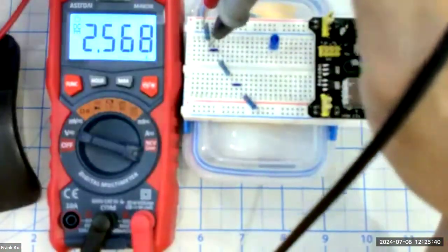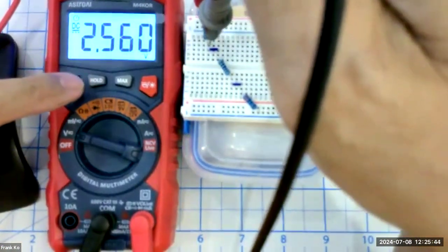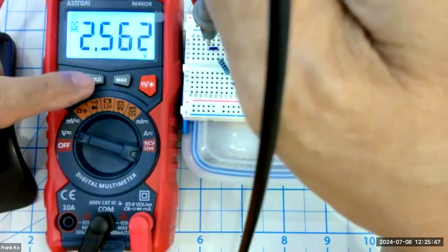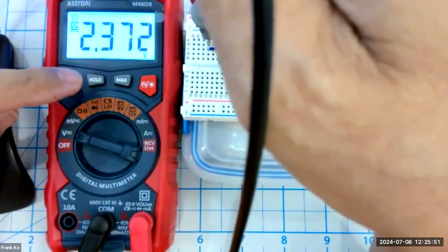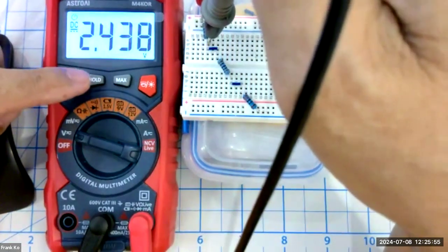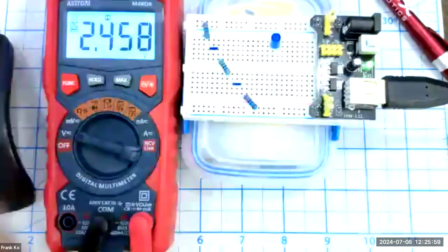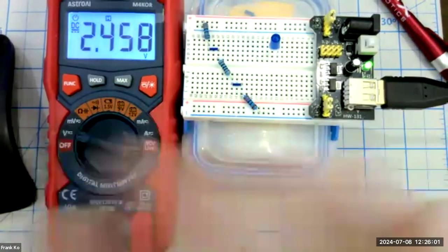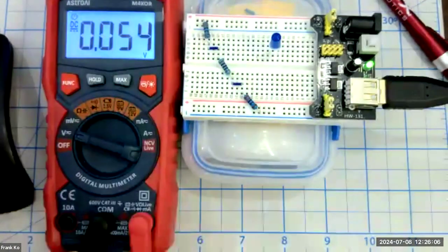Measure, put the probes into one hand, and with the other hand, hold steady. It'll jump around a little bit, but as steady as you can get. Press the hold key. Hold steady. Okay, are we close to the 2.54, 2.45? Not bad. Now let's go ahead, unhold, and let's do the second one.